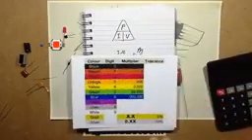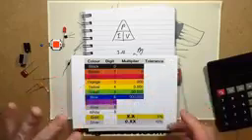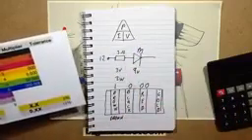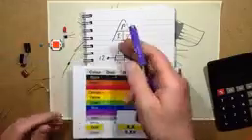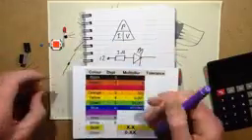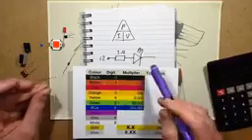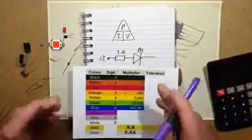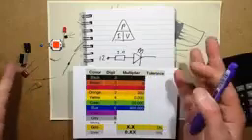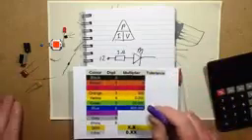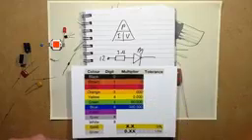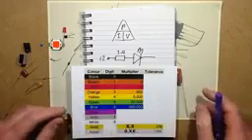That's just a summary. I'm not going to go into too much detail because it would get boring very quickly. But this is just the basics of what you need to know: how to work out the power rating of a resistor if you're driving quite a heavy load with it. In most instances, a standard quarter watt resistor is fine, and how to choose the resistance value to limit current to whatever you want through LEDs and things like that. So fundamentally, that's it. Hopefully that's helped, and I've not overcomplicated it as I sometimes do.